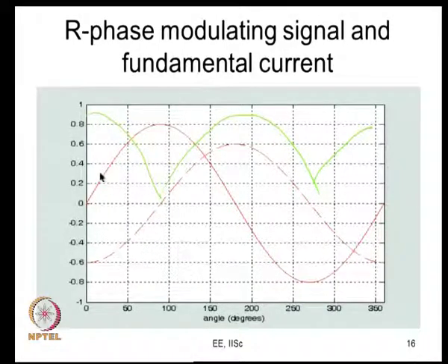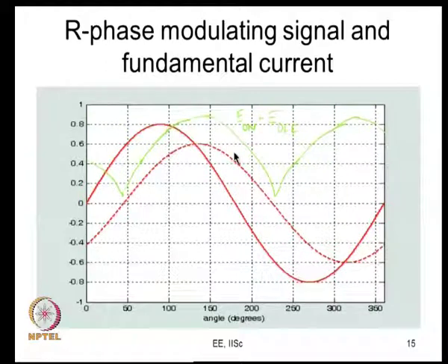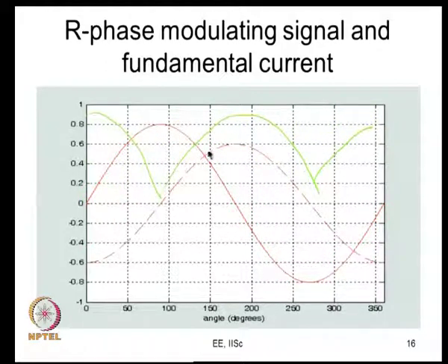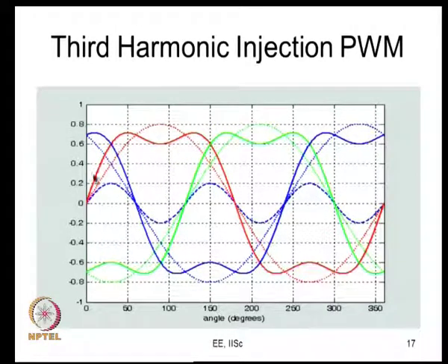Well, it might indirectly depend in the sense that the modulation index determines the output voltage and that determines the current. But it is a function of current, it is a function of the DC bus voltage, and it is not a function of power factor. So, you can see that for different power factors the average value is unchanged. This is for sine triangle PWM, and this is actually true for any continuous PWM. You can add third harmonic injection, that is any continuous PWM where your modulating signal is a continuous function of time. An example would be third harmonic injection.